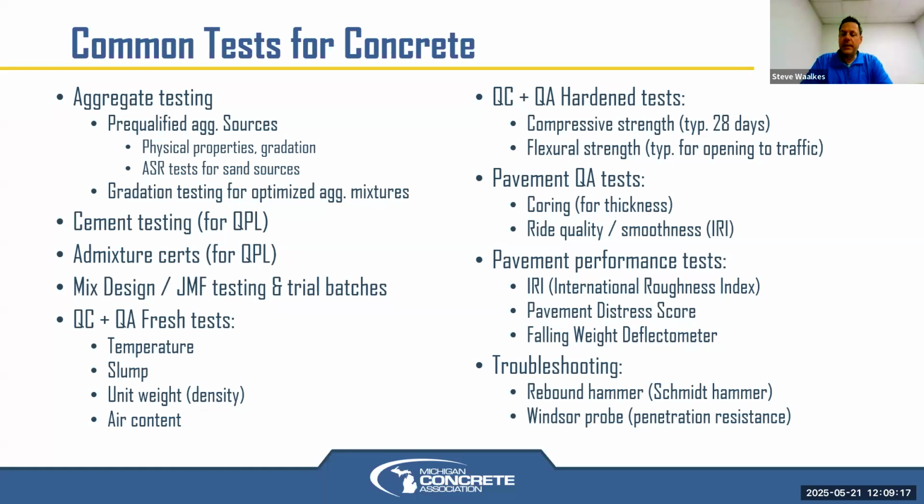For opening to traffic strengths, especially for bridge decks and pavements and things like that, and even driveways, drive approaches, and things like that, they'll do flexural beams for opening to traffic only, not for pavement typically, unless it's a concrete patch job. Then the opening to traffic beams suffice for the pavement as well.